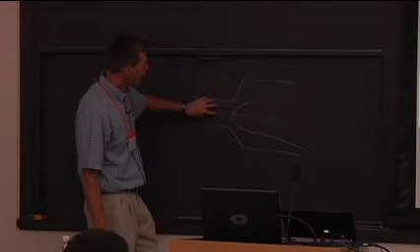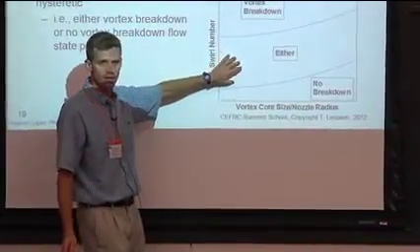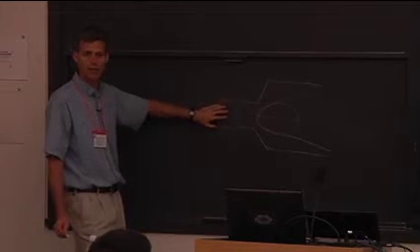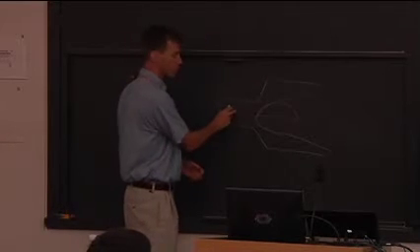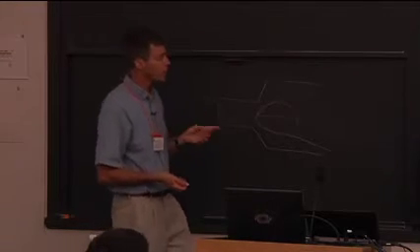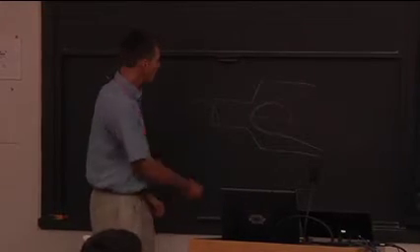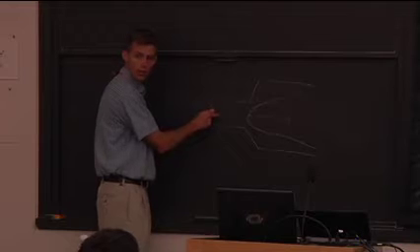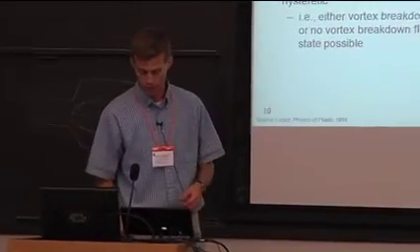But the flow in the nozzle passage is where you get this phenomenon: if the flow in the nozzle passage is sitting in this hysteresis region, the flow won't break down. It can have a non-breakdown state, but it also means if you whack the flow hard enough, you can kick it to that upper state on that top right diagram, and the flow can break down. All right, well, it's a straight pipe. There's really nothing to perturb it except for gas expansion. Suppose I could somehow introduce a flame into this nozzle section. If that can force a vortex breakdown bubble, now all of a sudden you have a low velocity region. So although on average the flow velocity is much higher than flame speed, I can locally create a region where the flow velocity is below, even negative. And that's basically combustion-induced vortex breakdown in a nutshell.